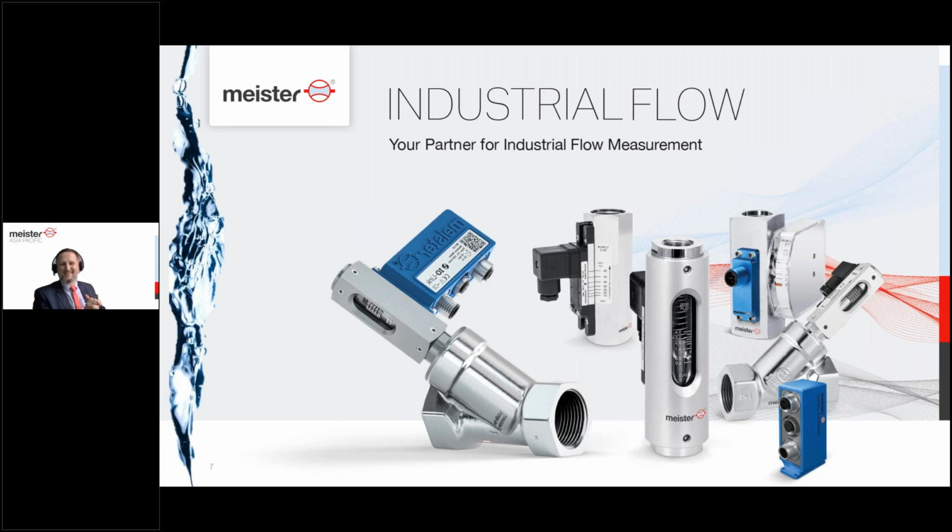But then also there are output options of an analog transmitter, which gives you the standard 4 to 20 milliampere or 0 to 10 volt output. That is the option we would see in the back with the small blue box attached, M12 connector. The latest product development then of Meister would be the digital output option, which you can see in the picture here in the front or also there,